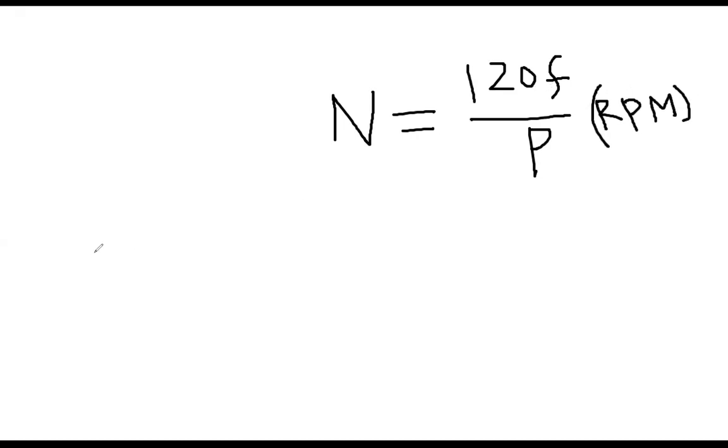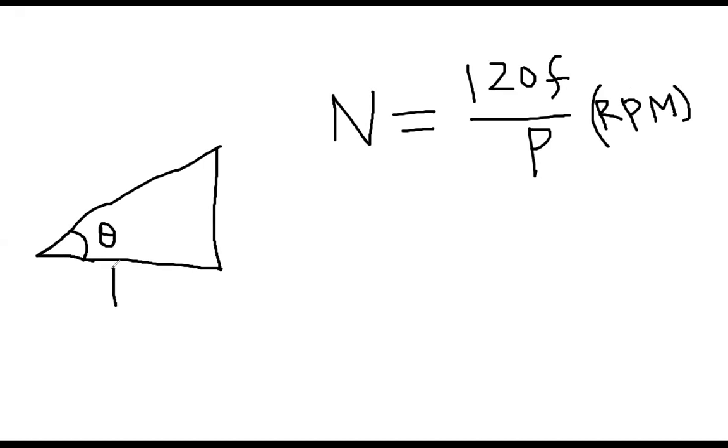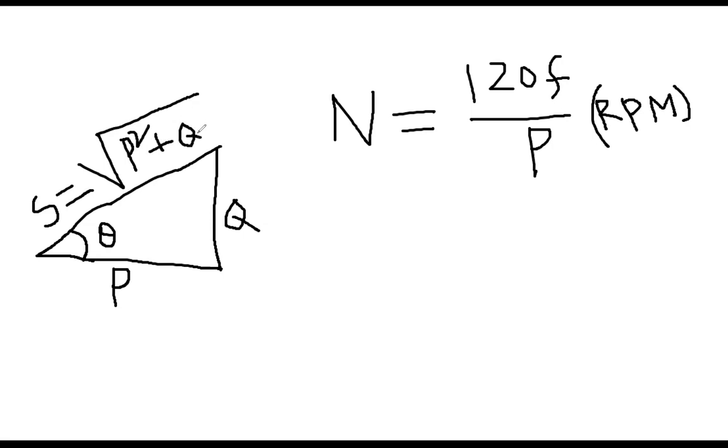And also you need to understand this one, because the question is to find out the power factor. This is theta. This one is the real power, this axis is the reactive power, and this axis is the apparent power. Therefore, everybody please write down this triangle in your note. Then you can find out the power factor.